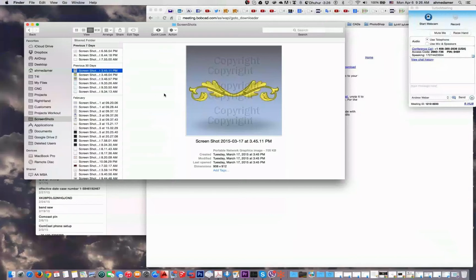Okay. And one more thing we are trying to know as well is the turning stuff, how to create turning models, like when I'm going to use my fourth axis, which is a turn, and how to do it as a wrapping or unwrapping, or as a 3D model.